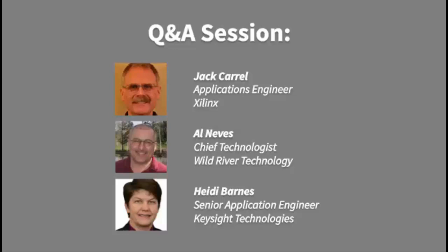Okay, here's our next question. How does the RCVR determine the proper combination of equalization and settings of CTLE, FFE, DFE to optimize channels? I'll take that. Yeah, thank you, Jack. The Xilinx receivers have an auto-adaptation algorithm in them. It is proprietary, but from our testing, we can set that algorithm up to choose the best tap settings for the equalizer. And also we have a wizard tool for when you're programming the FPGA, that if you can feed it some of the characteristics of your channel, it can preload some of those settings and achieve optimization.